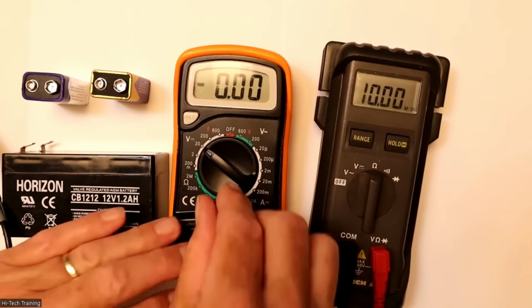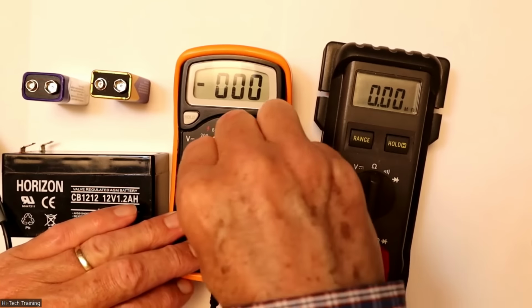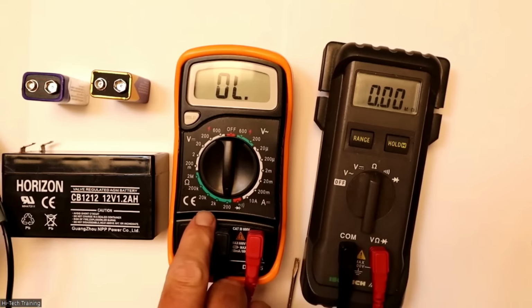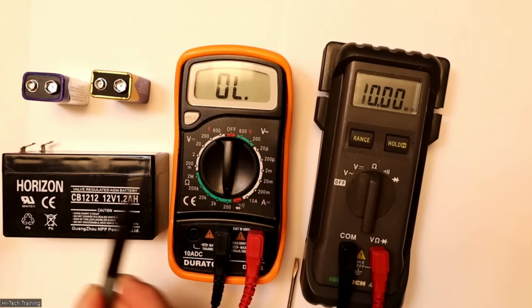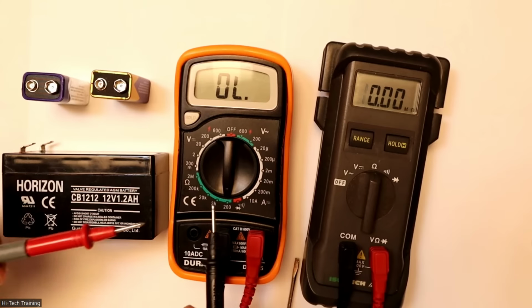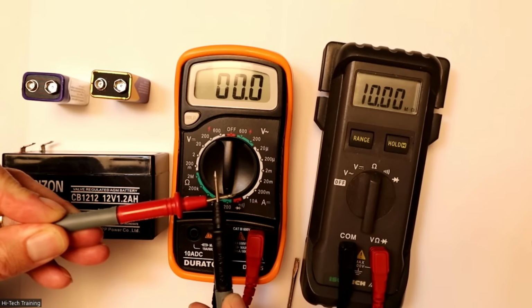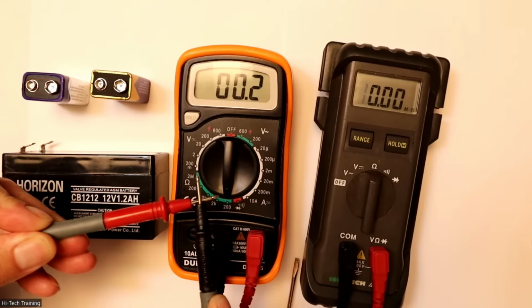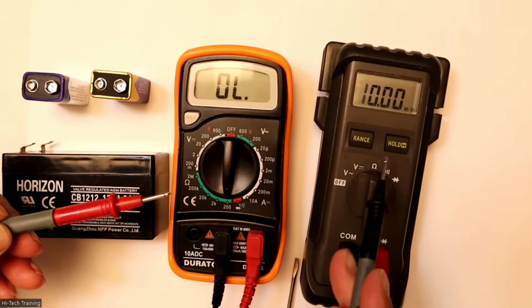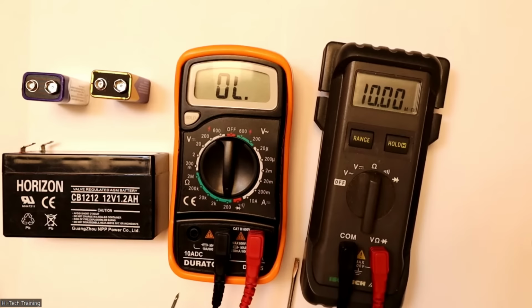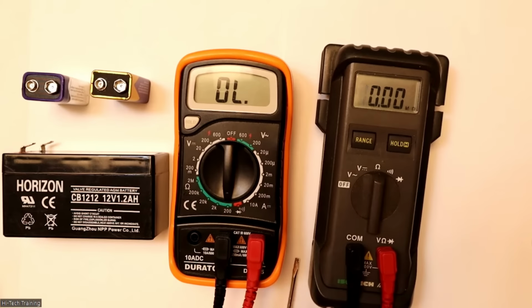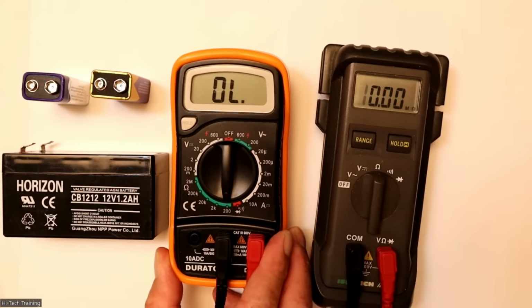And let's go on this meter for ohms here, like maybe the 200 ohm range. You always start in the low ohms range and work up on a meter that has ohms on it. So come on here, and we're reading, it should be around 0.1 of an ohm, which is good, maybe 0.2, and it'll read OL there, whereas this one just reads millions of ohms, okay? So again, every manufacturer will have slightly different ways to display the resistance readings for you.